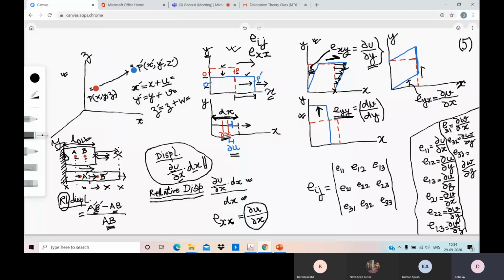But one thing you please note, that the displacement is not only that. When this is happening, there is also a displacement along this direction, which is EXX. EXX in negative direction, if the constancy needs to be maintained. So as a body is stretched, its cross section or its thickness or width also has to come down.